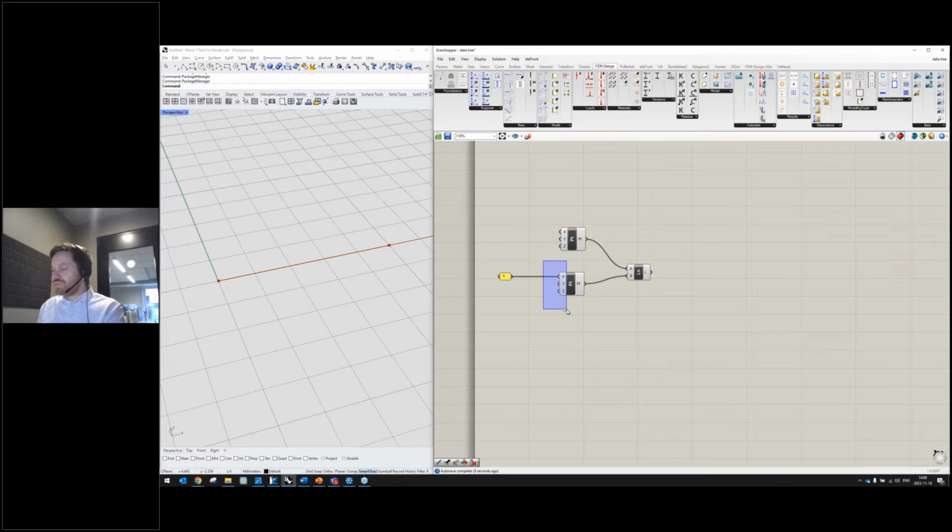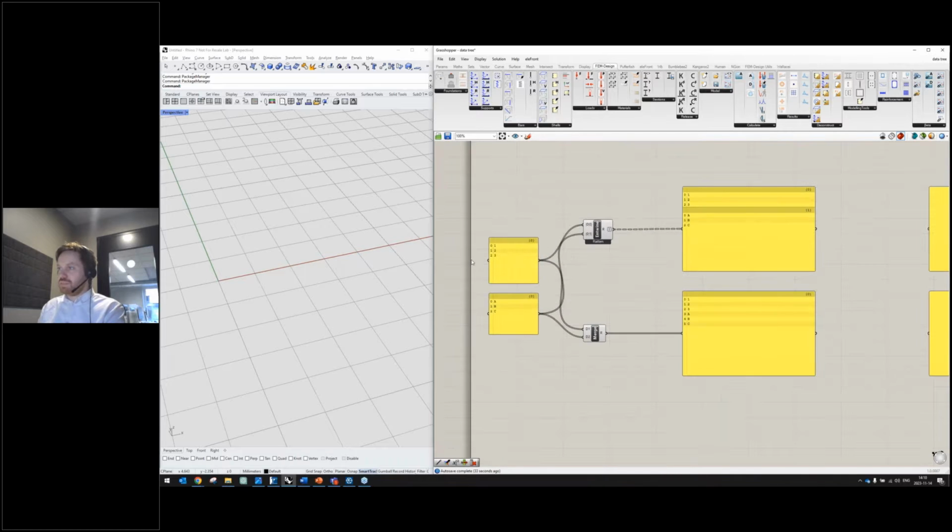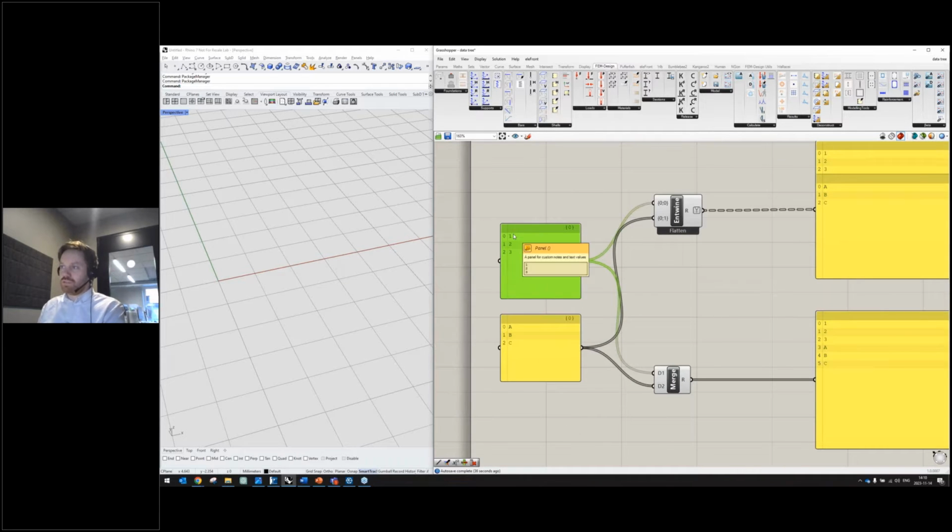So you have the inputs on your left-hand side and the output of that tool or function, or whatever you want to call a component, on your right-hand side. This way you build up your script, and you don't need to write any code. You can just search for a component and connect different components to create a script. When you're doing this, you end up working with lists in different ways. Here I have a list containing 3 different values, number 1, number 2, and number 3. And here you can see the position in the list for the different values.